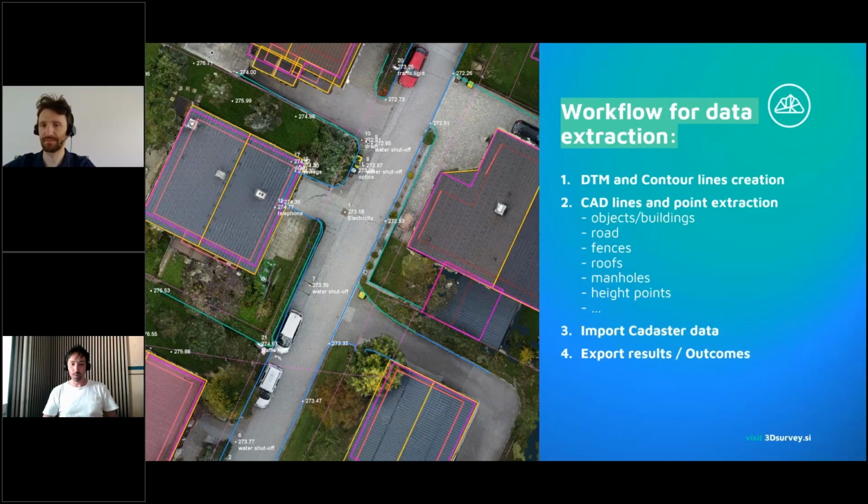We will show you, while extracting all these details, all the tips and tricks which you can use during the data extraction. And then at the end, we will also import cadastral boundaries in 3Dsurvey, a new super powerful feature: the 2D DXF to mesh to 3D mesh transform tool. So you will see this at the end. And nevertheless, how can you export the results or create a PDF from everything you created?